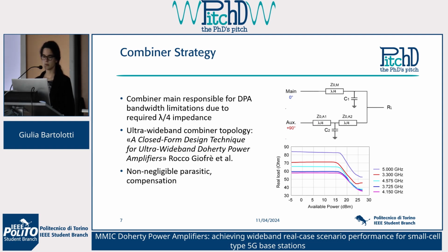This solution for an ultra-wideband Doherty was first applied in the case of hybrid circuits, and also to a single-stage topology. So this was the first time to apply it to an integrated circuit and to a two-stage topology. Also the parasitics were included. On the bottom right, you can see how we effectively manage to achieve a load modulation, so a change in the load seen by the main for all the frequencies in our band.